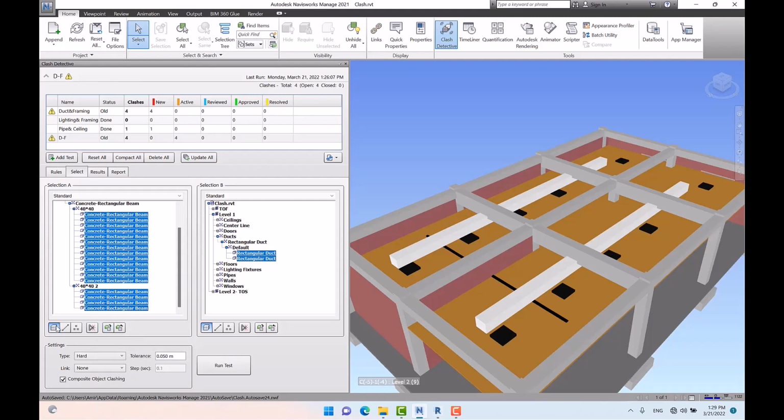For example, the first one is surfaces, which includes surface geometry in the clash test. A clash test without surfaces does not make sense. So we should always select this, since the geometry of the objects is going to be checked. The next one is lines, which includes line geometry in the clash test. You may wonder, okay, what is a line? Guys, when we import a file from AutoCAD to Navisworks, all of the objects are recognized as lines. If I want to clarify it more, suppose that somebody has drawn the pipes in AutoCAD by using lines. Following that, you want to check the lines in your clash detection test in order to find the intersections, so you should check lines. But if you do not select line here, the intersections which are related to the lines are not going to be reported, so you can use it while you are importing a file from AutoCAD.